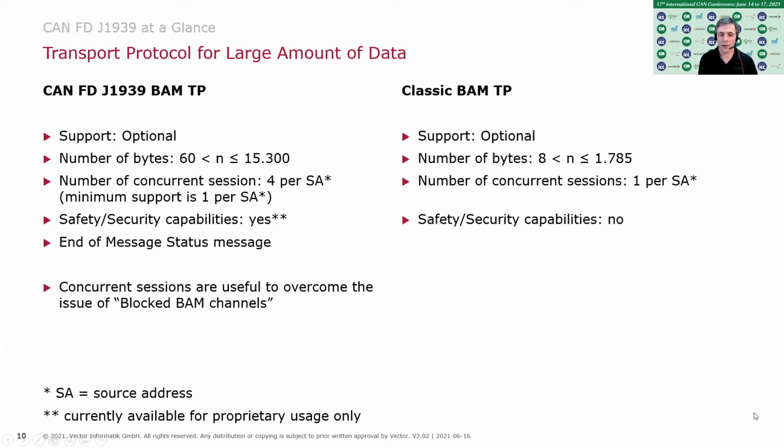If the system is not healthy, the diagnostic message needs to be transmitted every second, and if there is a large number of faults to report, it more or less blocks the only available BAM transport protocol slot. Now a controller can use up to 4 of those transmission slots, which gives you the freedom to block neither the application control data nor the diagnostic data.